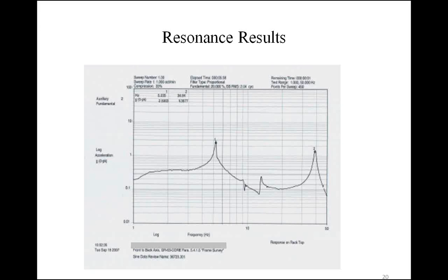This is what might result from that test on your product. And this is the most important result that somebody is going to want, because you can see that there's 3 main resonances that occur, and those are the frequencies that are going to be the most critical for you to match to the field and test in the lab, and then improve it.